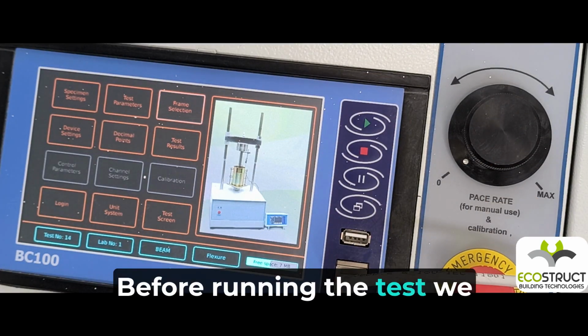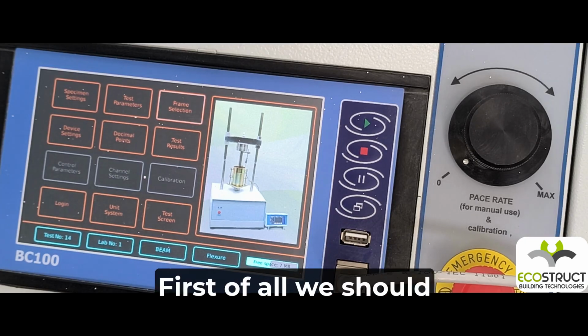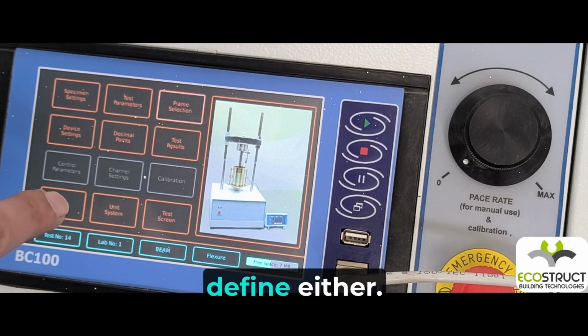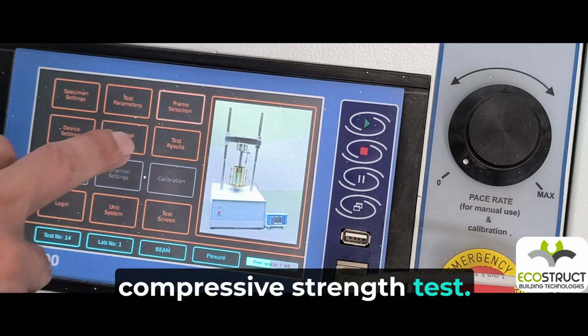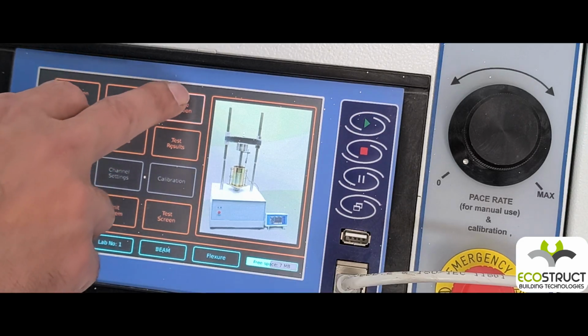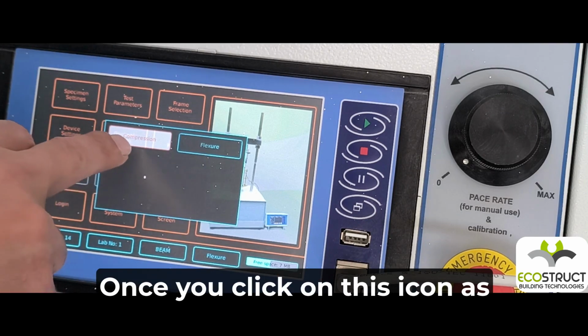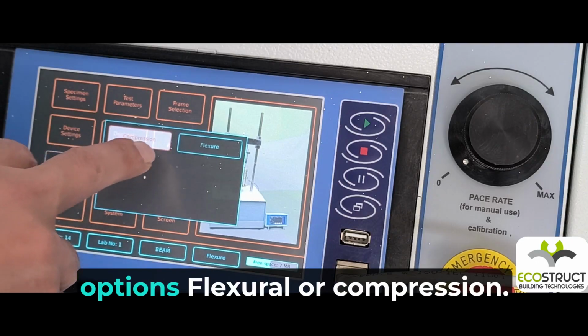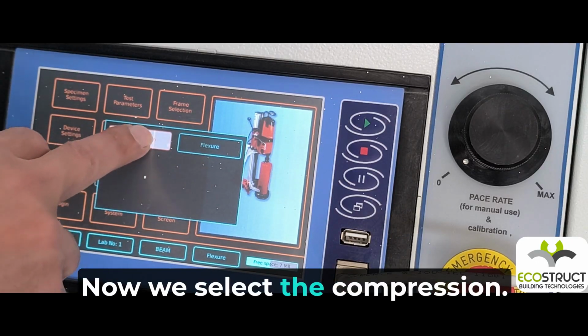Before running the test, we should adjust the settings of the machine. First of all, we should define whether this is a flexural or compressive strength test. Once you click on this icon, as you can see, there are two options, flexural or compression. Now we select the compression.